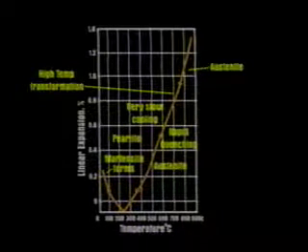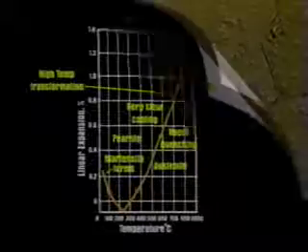It should be noted that martensite occupies a larger unit volume than austenite and the other microstructures formed from austenite. Such dimensional changes during heating and cooling have been measured and are illustrated by this curve. Here we see the steel decreases in size with cooling, which is expected, until martensite is formed. At this time, there is a corresponding increase in the dimensions of the steel due to the large crystalline lattice structure of martensite. This dimensional expansion is one of the main reasons for distortion and cracking.